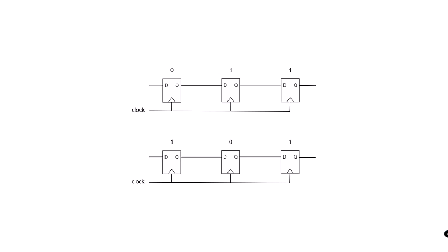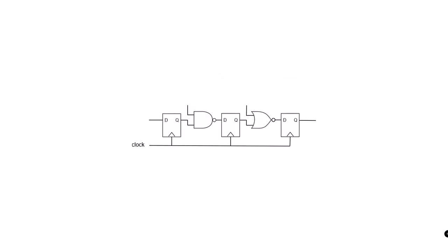The sequential model of operation is more abstract. It establishes order to the operation of the machine. The sequential model consists of a series of digital state values. A clock signal controls when each register reads a new value from its D input and stores that value. Sequential state is not continuous. The state jumps from one vector of digital values to another.